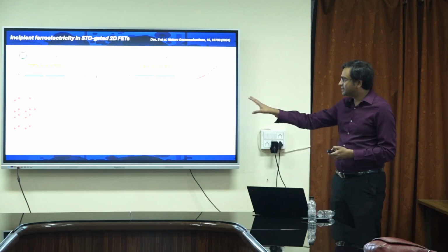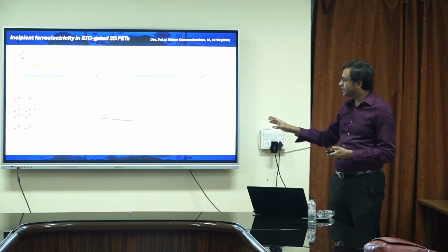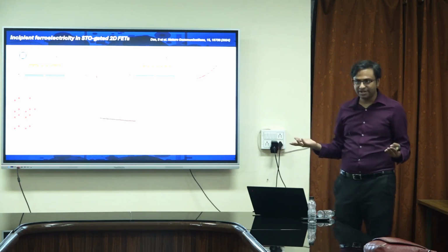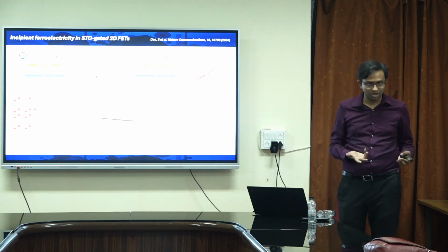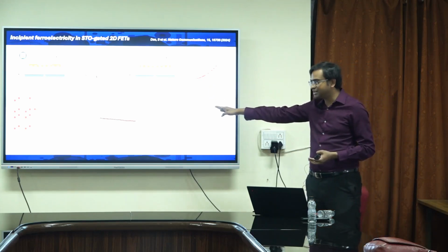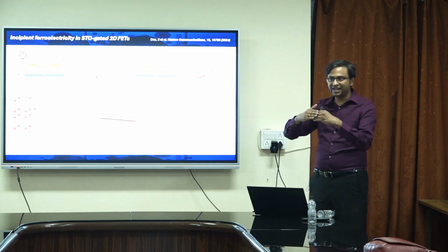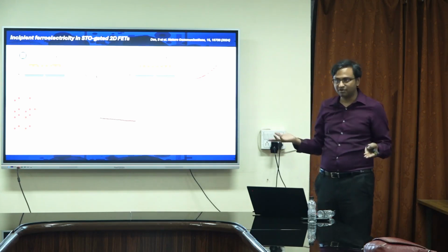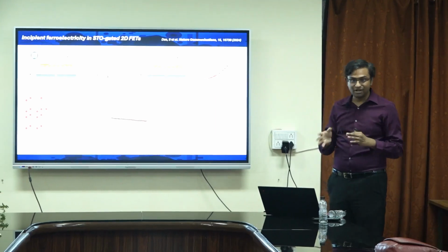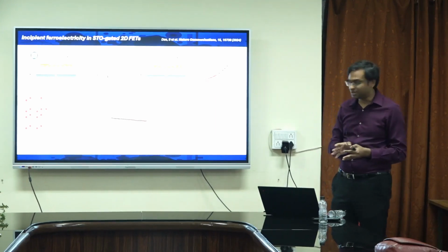And there are certain ideas about this particular ferroelectric, but then you have to look into retention. As I told you, a memory device has to be retentive. Otherwise, what is memory if I cannot retain it, right? But now you see there's some problem. You see that the high conductance state is going down. That means after some time, the memory states will merge. That means I have forgotten everything, okay? Which is somehow good for some brain application, brain-mimetic application, right?